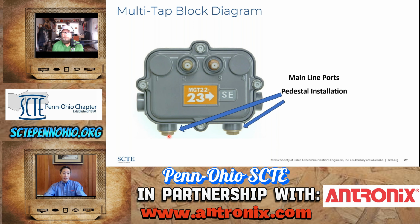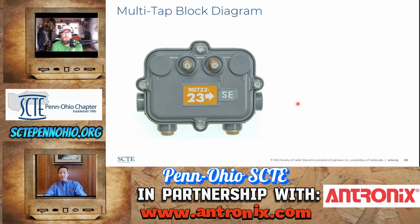You would remove these hex port plugs and put them on the other side, but connectors can go in and out. So this left side would be the in, right side would be out, and the arrow is the direction of the main path going from upstream to downstream, from the head end to the home, down the network. Now, the truth is you can install these in any configuration. We've seen them in multi-dwelling units, MDUs, apartment buildings, where either port on the left or right can be used. And the beauty of these is they're configurable relatively easily to use either port.